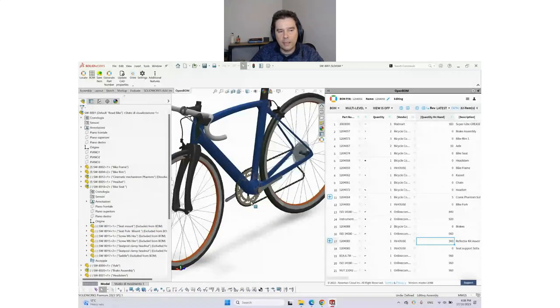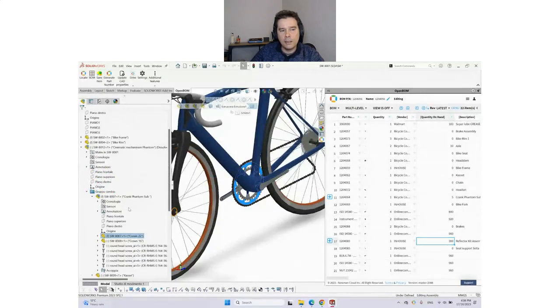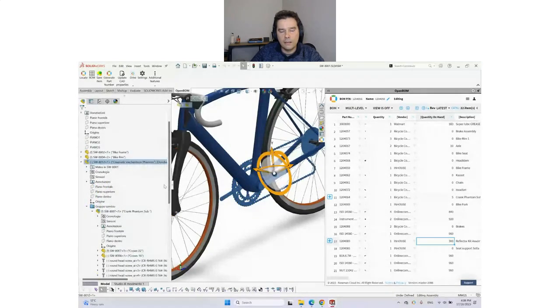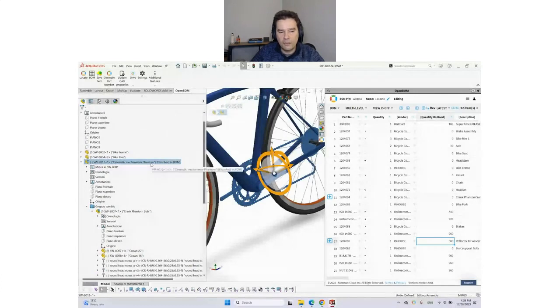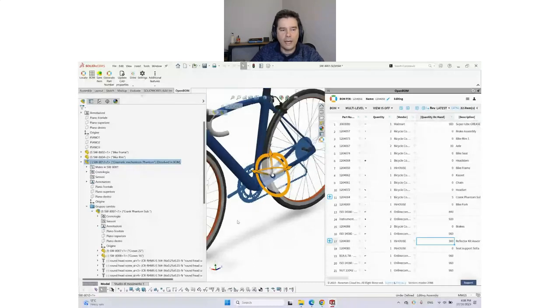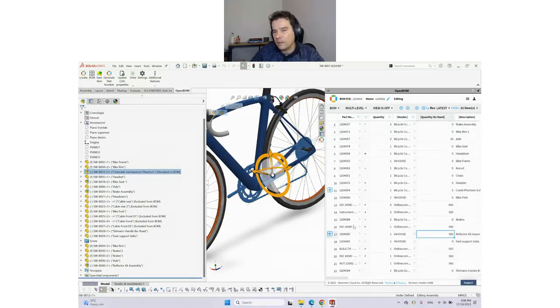The same with some phantom assembly. So look, there is an assembly in your CAD tool that doesn't exist physically. You don't assemble it, you don't track it, you don't have a part number for it, you don't have any routings, any operations, or you don't want to track any cost for it. So it is dissolved in CAD, and when you bring this assembly to OpenBOM, we bring the right level. So this bill of material you see here already has the right levels in terms of assemblies and sub-assemblies that you're going to produce, assemble, track, cost. It's closer to a planning or production bill of material than what you have for drawing purposes only.